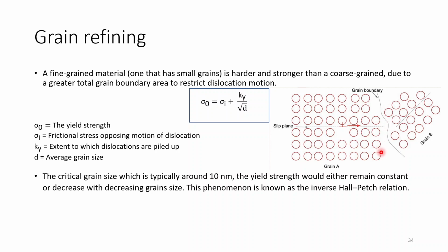So that means, ma'am, the temperature is one of the parameters? Yeah, cooling rate is one of the parameters. So how fast you are cooling your material matters, because if you are cooling very slowly, then a lot of time will be there, so growth will be higher, so a smaller number of nuclei will be there. So it depends on the cooling rate basically.